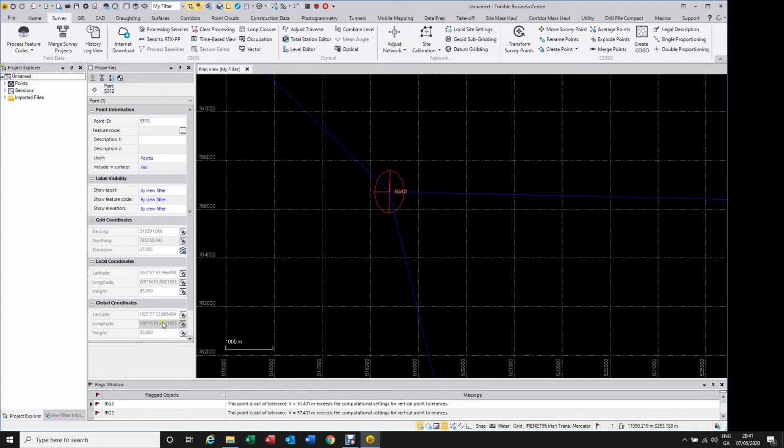That's why the new ITM coordinate system is GPS friendly. Basically the GRS80 ellipsoid is in a good relation to the WGS84. It's almost the same. You see the geoid was added, so ellipsoid height, this is elevation from the geoid. If you compare the two, you see how much the geoid is above the reference ellipsoid. That's just something you can see on these coordinates.